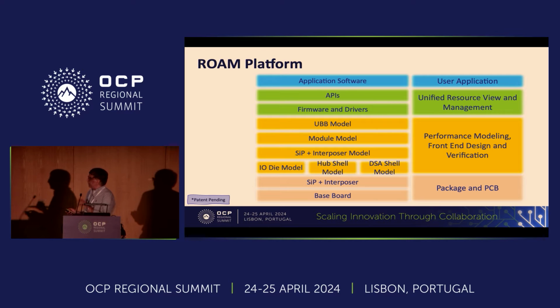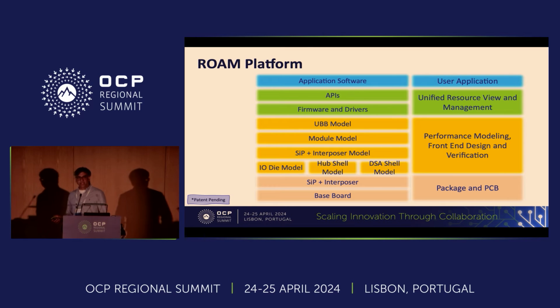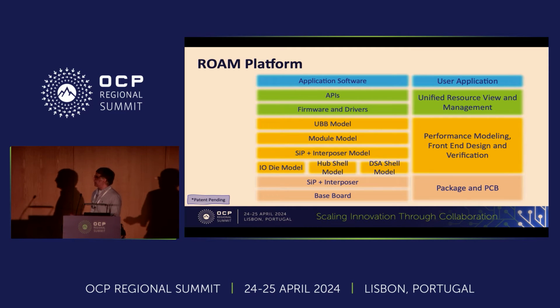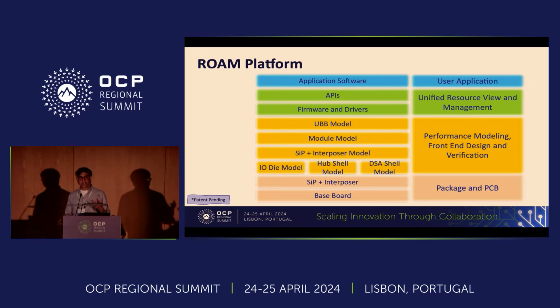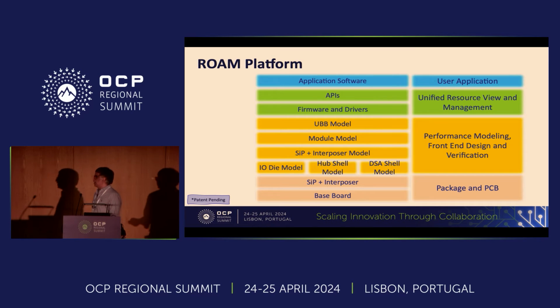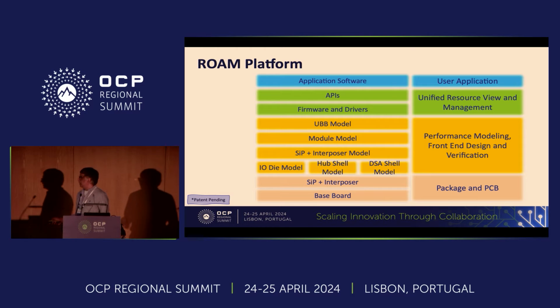I'll show you examples later of the SIP, but essentially the way I've been thinking about it is it needs to be a full platform. So you have the baseboard, and then there is a system in package, which can be organic substrate based, or if you're doing advanced packages, then you need an interposer.